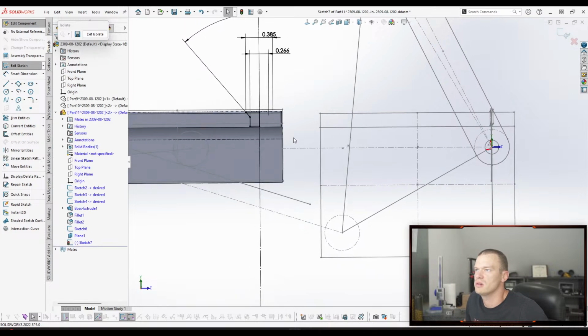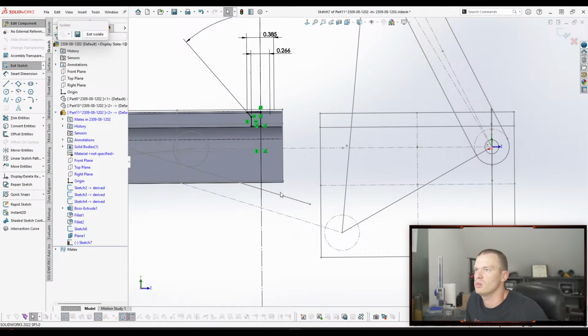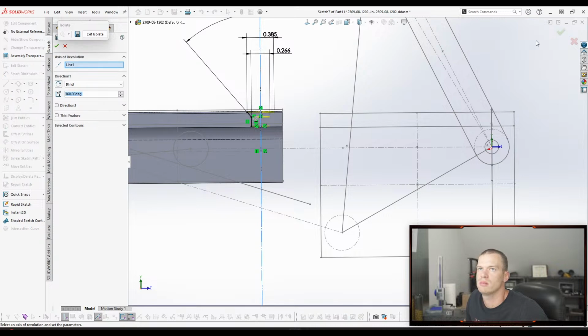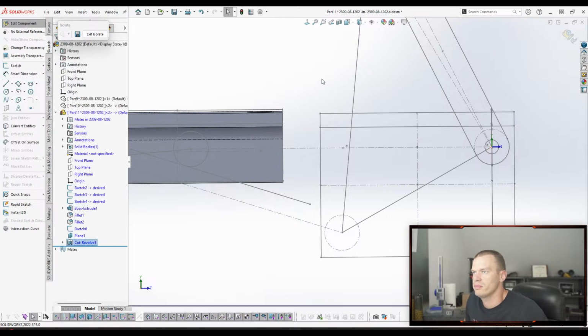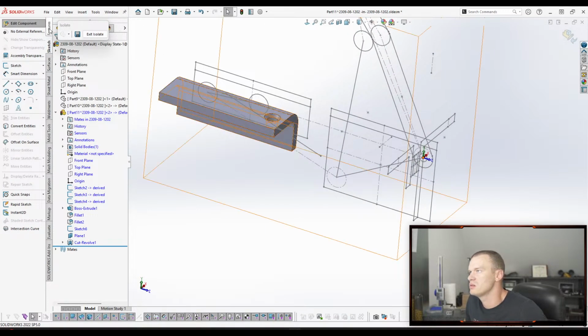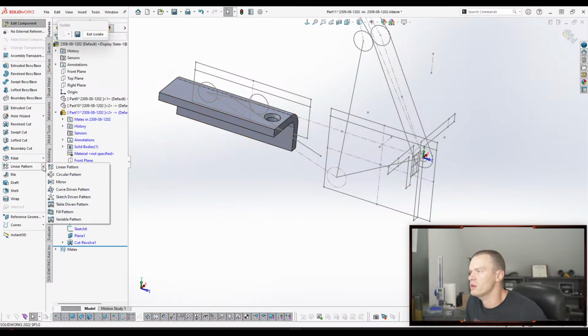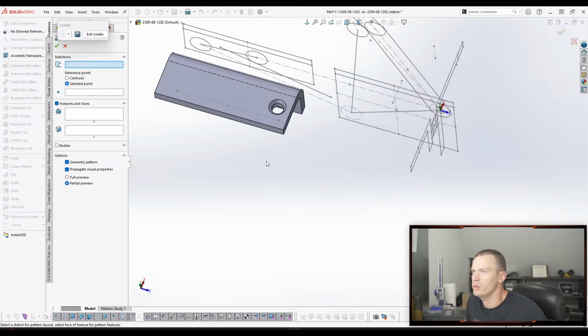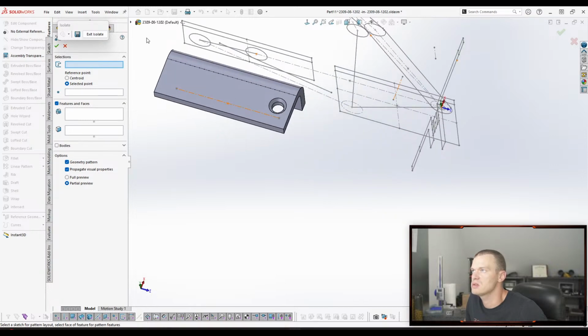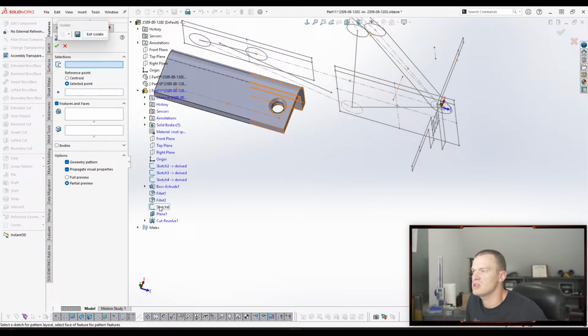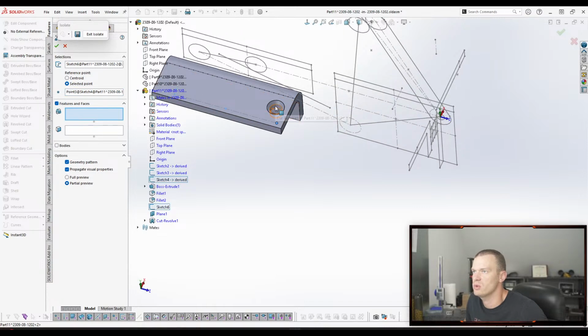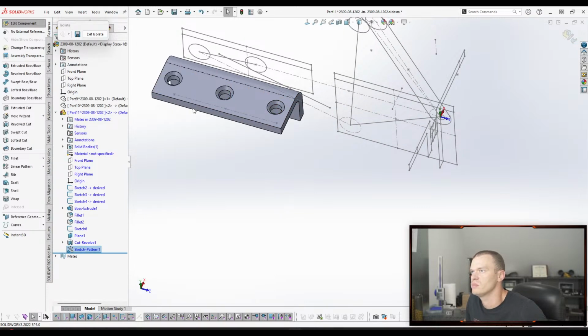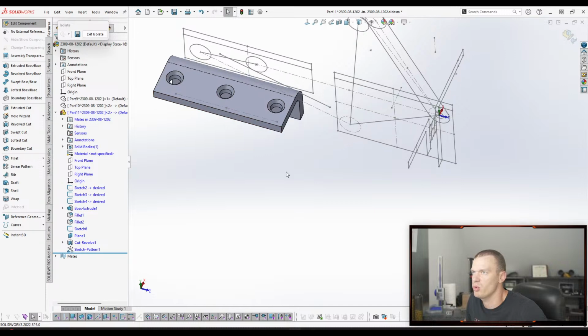So we'll put this in here like this, and then it's a revolved extrude. And now only draw things if you have to, and we don't have to draw that again. Now we'll just use that sketch-driven pattern. What we want to select now is first the sketch that has just the points in it. Then the selected middle point is here, and the geometry we want to pattern is this. So now we get 3 of them that are tied to those points.